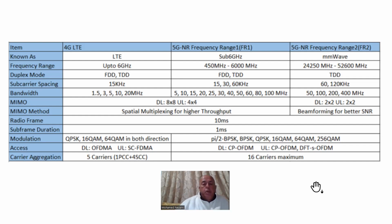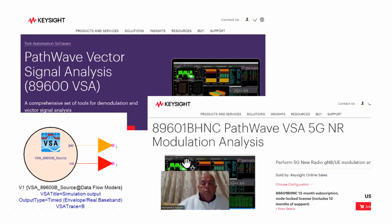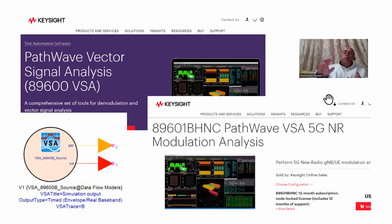And the reason for this, as I will show you in a minute, is that if you're going to use a real 5G waveform, then you really have to demodulate an entire 5G signal. And so you want to make sure that you're not impairing. How do you isolate and look at the transmitter-alone impairments in terms of EVM and in terms of power spectrum and other things? So what I did here is I started first by running just a plain 200 megahertz channel of QAM signal, okay, and trace the EVM throughout the system.